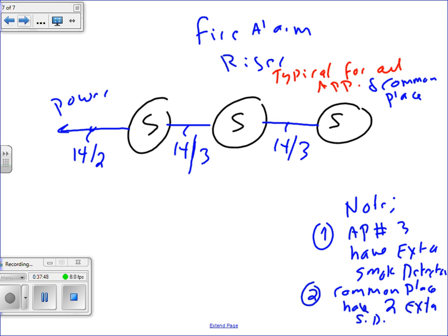No, the code doesn't talk about these. No code references. If you're looking for an NEC code reference, the closest you can get is an article that talks about, I think, Article 760, fire alarm system, but it doesn't say anything about the risers. It just tells you the type of wire that you use, plenum rated wire versus riser wire. So it talks about the type of the wire. It really doesn't tell you risers.